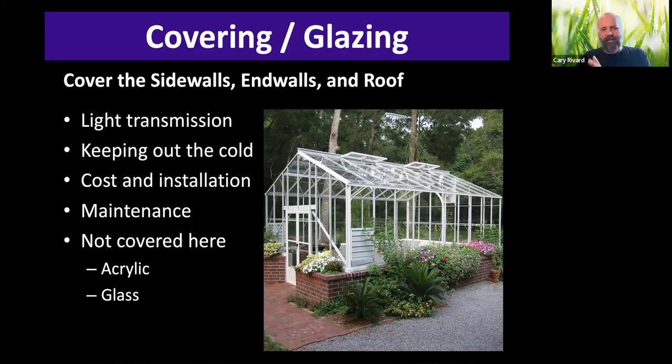I could tell stories, but there are greenhouse businesses that have gone bankrupt because they had glass greenhouses. A big hailstorm came. They could never afford replacing all those glass panels. Not to mention the mess and the potential danger, right? And so we want to stay away from glass. Acrylic is also glazing that's used for very, very high dollar greenhouses. I don't think a lot of our beginning farmers are going to be using that, but if you're interested, you can look up acrylic or plexiglass glazing as well.